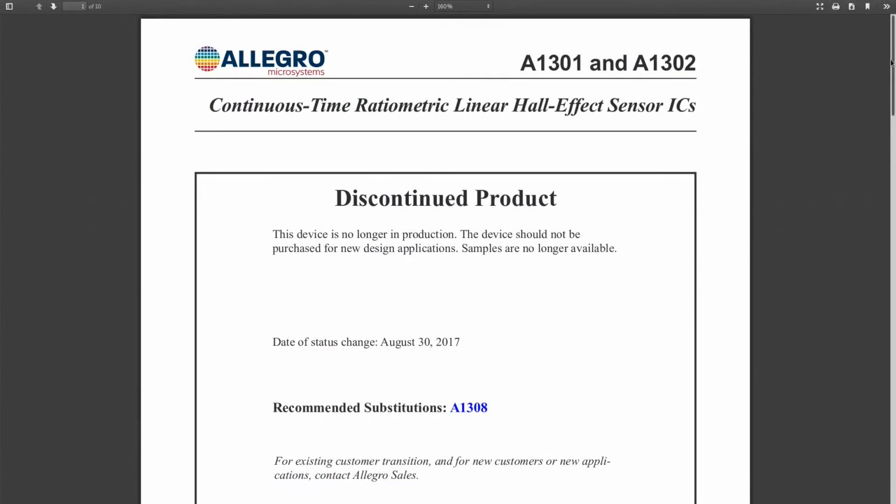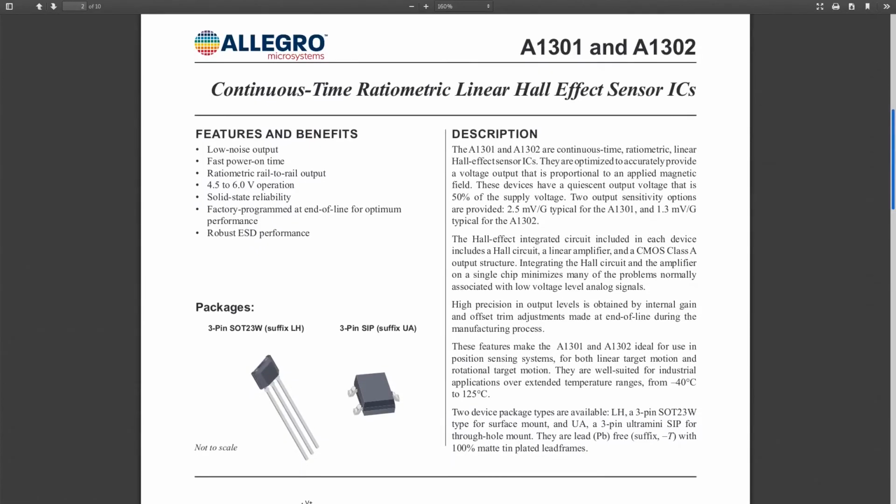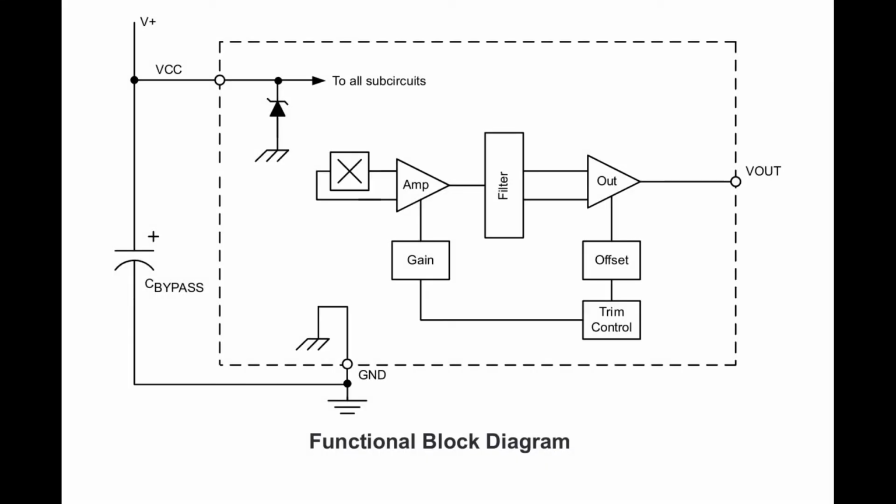While this is a simplified way of explaining the Hall effect, it does cover the main points. In practice, Hall effect sensors like the A1301 that I'm using for my electronic valve instrument project have a bunch of other stuff inside their packages, like amplifiers and filters, to make up for the fact that the Hall effect alone would not be strong enough to drive an external circuit.